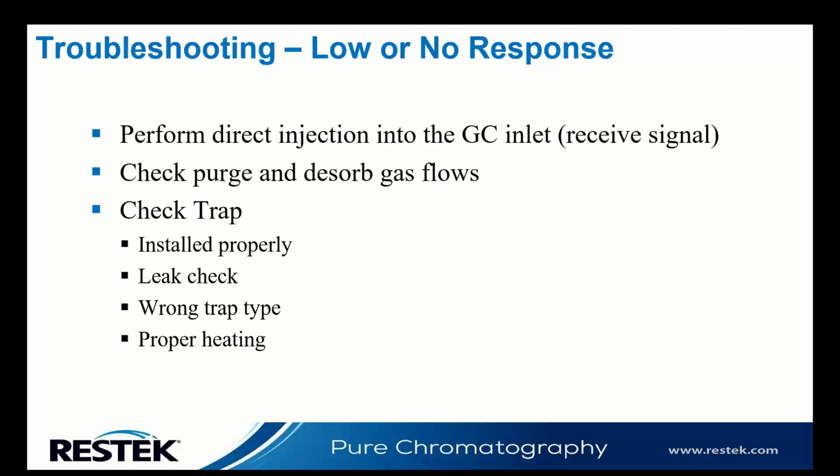We can check our temperatures, make sure that our system is actually heating up. I mean, I had that happen once. I don't know if anyone else has ever had it happen, but I had a trap that wasn't heating up. And of course, I couldn't figure it out. So someone else came in and figured it out very quickly, which was a little bit embarrassing because it wasn't even something that I thought about. I was like, somehow the compounds are disappearing into thin air. We purge them and then they vanish.